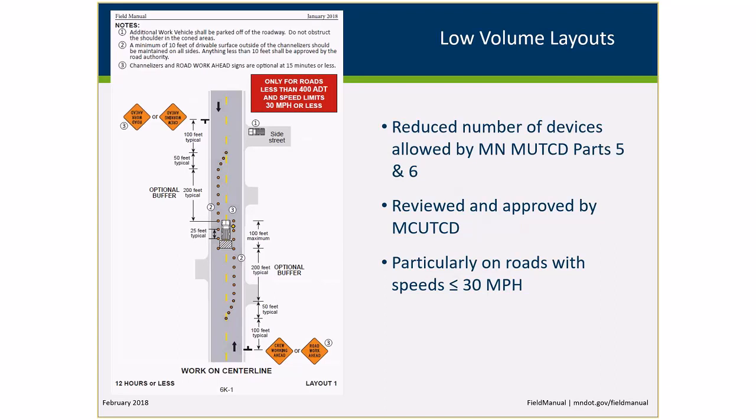See specific note number 3, where it talks about how the channelizers and the road work ahead signs are optional if you're out there for 15 minutes or less. So normally, for work on center line, if you're out there for up to 12 hours, that's what it means on the bottom left corner, what the duration of the layout is appropriate for. If you're out there for less than 15 minutes, you wouldn't need to put out the channelizing devices or the road work ahead signs.